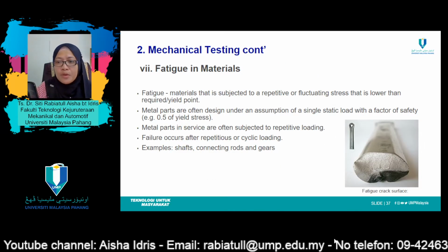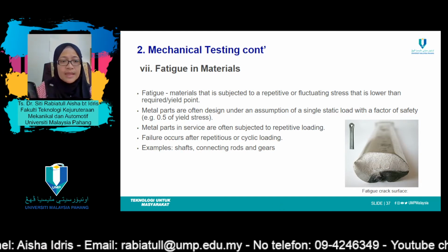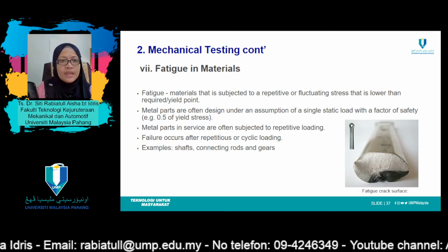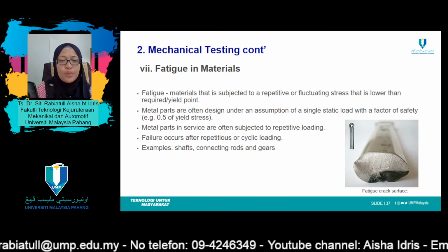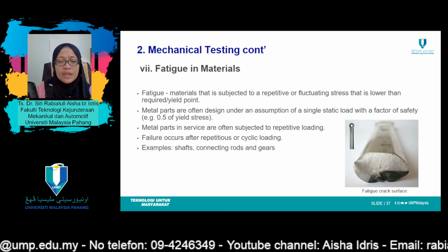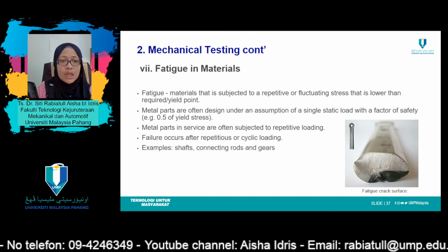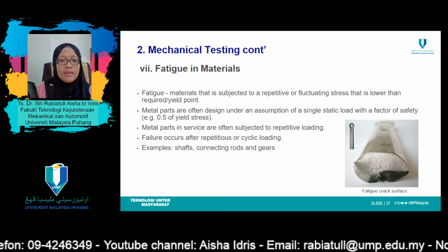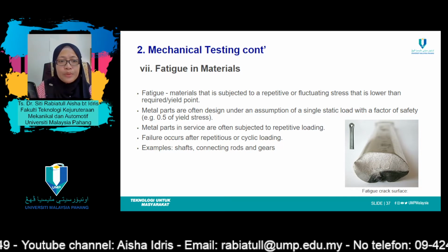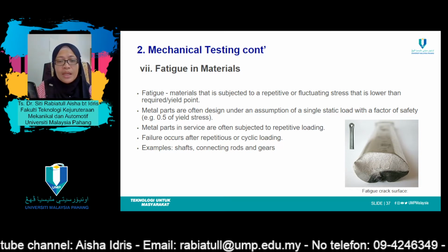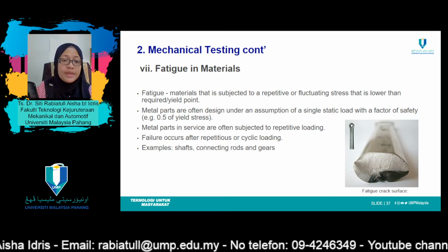Okay, so move on to the next type of testing, which is a fatigue test. Fatigue test helps in determining a material's ability to withstand cyclic fatigue loading conditions. By design, a material is selected to meet or exceed service loads that are anticipated in fatigue testing applications. Cyclic fatigue tests produce repeated loading and unloading in tension, compression, bending, torsion, or a combination of these stresses.